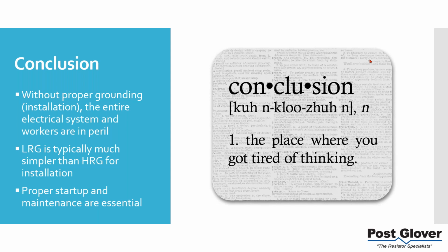As far as the process to do it without our unit, I would recommend creating a fault through a test resistor. Essentially that's what we do inside our system, but that's what you'd have to do without our system. So you'd have some kind of test procedure. If you're interested in knowing exactly what that is, we can give you that literature, but the point is that you're creating a controlled fault through a test resistor, and you're looking to measure how much current is left over from the resistor, so that you have your leftover charge current value.